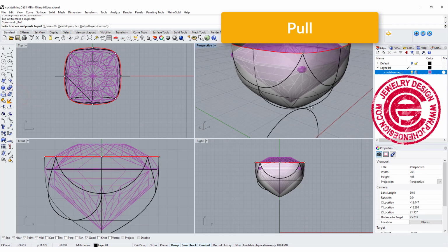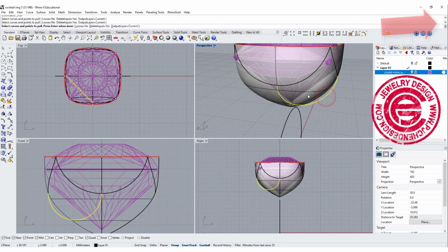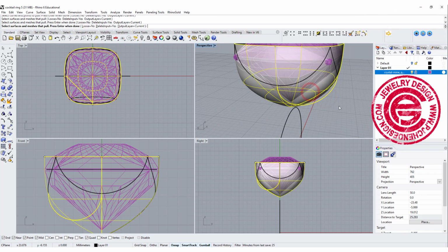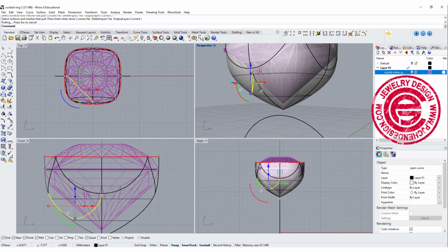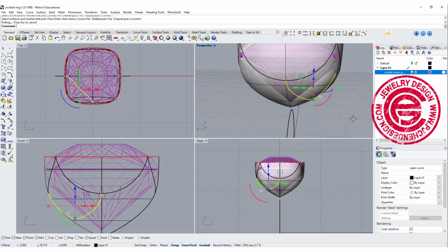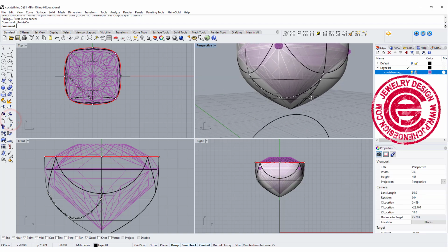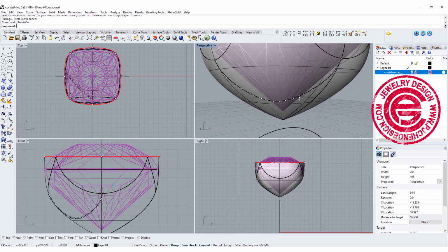And if you are interested in the difference between those two, I do have a video for it. So we are going to pick up this curve and click on this surface. So we'll get something like that. Depends on how you like it, and if you don't like it and you want to change it, you can turn on the control points, and as you can see, you have a lot of points there.